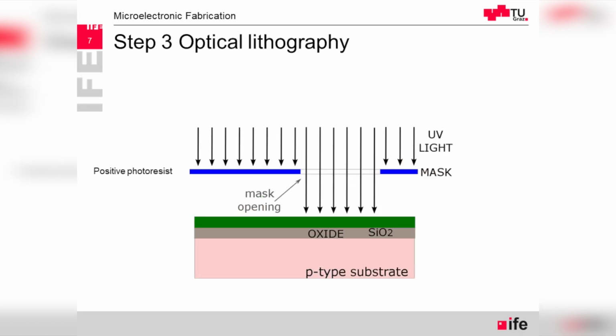There could be a separate lecture about photoresist. There is the whole art of the chemistry behind. It's also the thickness, the quality. It all influences how well you can do the photolithography. So I will just stop at that, saying we can have negative or positive photoresist, and if illuminated with ultraviolet light, such photoresist, it's easy to remove from this area.